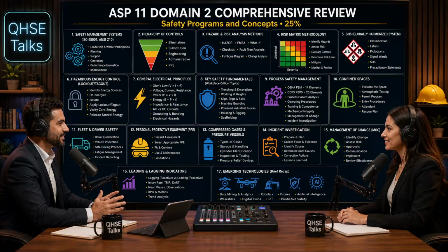Which leads perfectly to my next question about the electrical panel itself. When a circuit breaker trips because the amperage exceeds its rating, what hazard is it actually preventing? A lot of people mistakenly believe a standard circuit breaker protects human beings from electrocution. That's what I thought for a long time. It does not. A standard breaker protects the physical building from fire. It is designed to interrupt the circuit before the wires inside your walls overheat and ignite the surrounding materials.